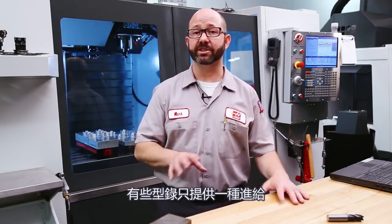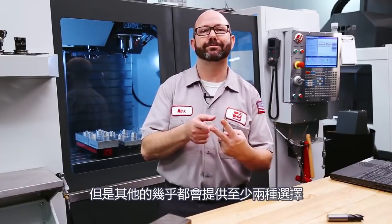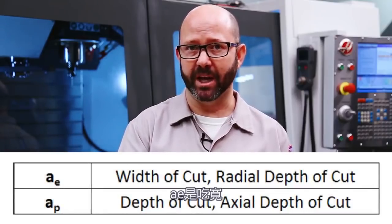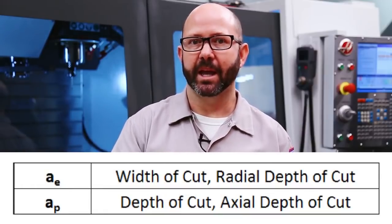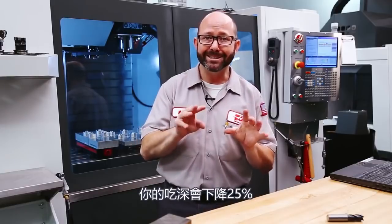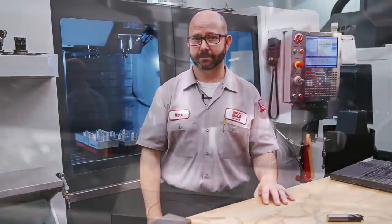each and every minute. Some manuals will just give out a single feed rate for all cutting conditions, but most will give us at least 2 possibilities, one for slotting and one for side milling. Our AE is our width of cut, that's our step over, that's our radial depth of cut, and our AP is our axial depth of cut, how deep the tool is moving in the Z-axis. Most times, if you're slotting, your bite is going to be about 25% less than if you're just side milling.